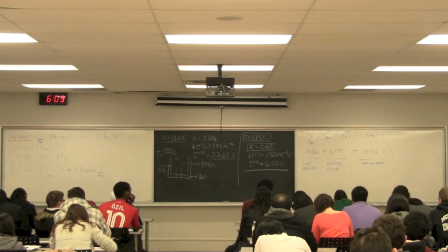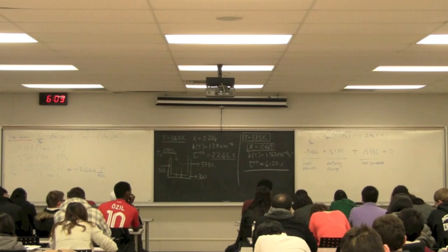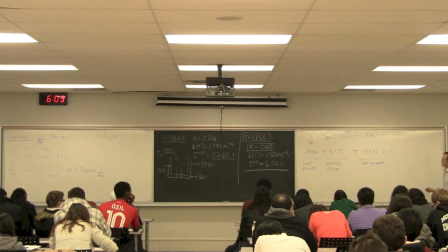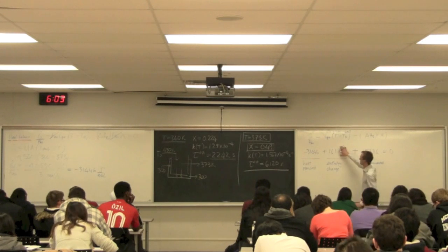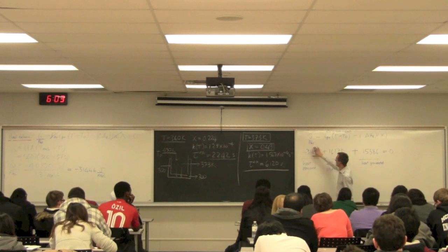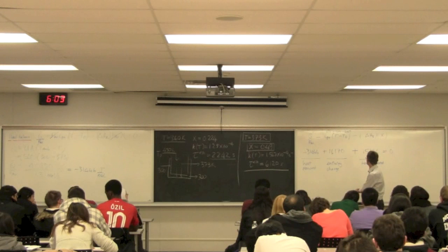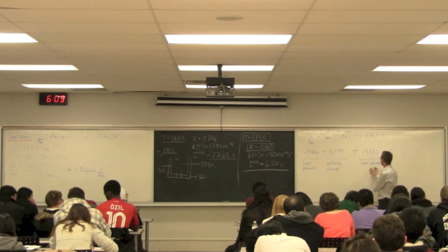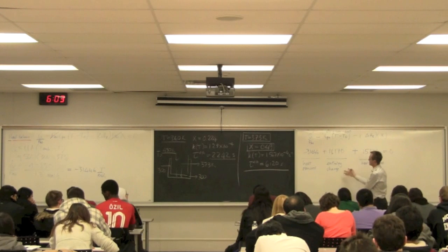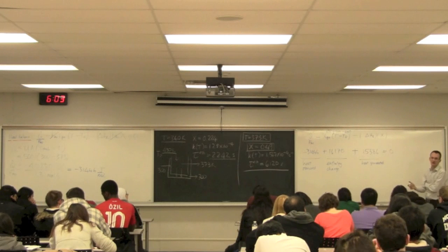This material is coming in at 450 Kelvin and then leaving at 373. That's what this big enthalpy change term is representing. So when we're removing heat, we're removing 30,000 joules per mole of heat. We're only generating about half of that from the heat generated by the reaction. The other half comes from actually cooling down the material.